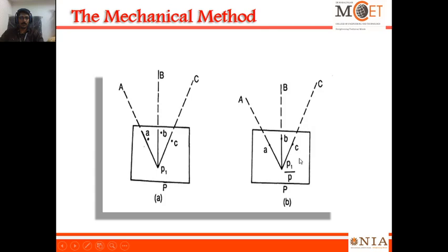Try to unclamp the tracing paper and rotate it in such a way that these lines exactly touch the points A, B, C over the actual map. Keep the tracing paper and mark the P by pricking with a pin over the tracing paper inside the drawing sheet.